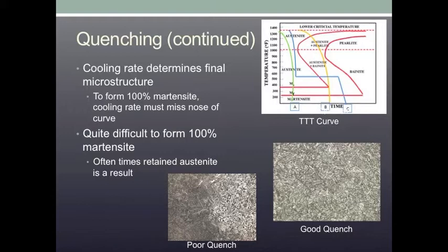Ms is the temperature at which the first martensite forms, and Mf is the temperature at which the final martensite forms. It is difficult to get a structure that is 100% martensite, so Mf often refers to the temperature at which 90% of the structure is transformed into martensite.